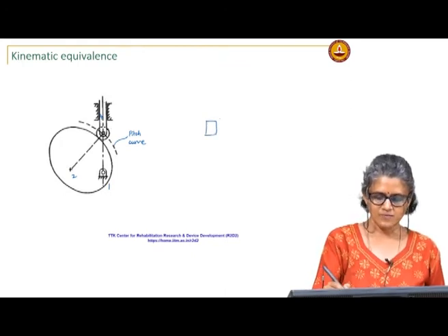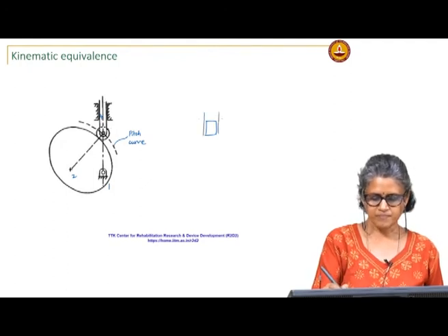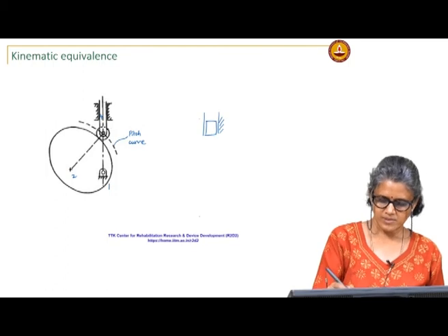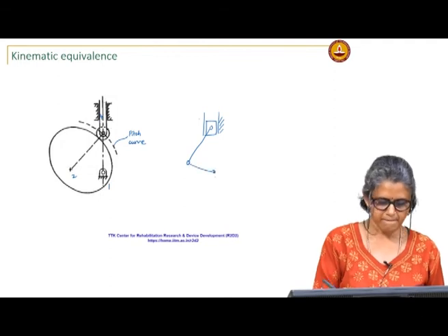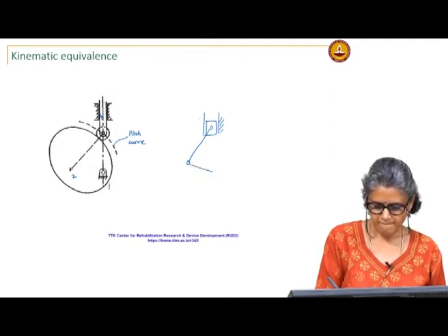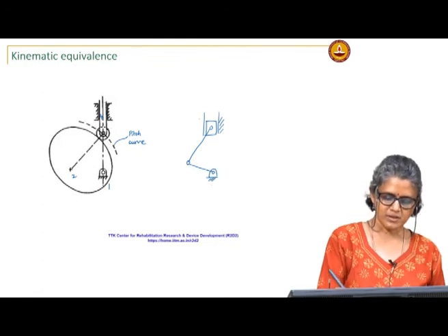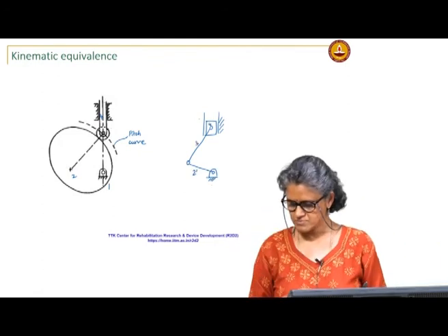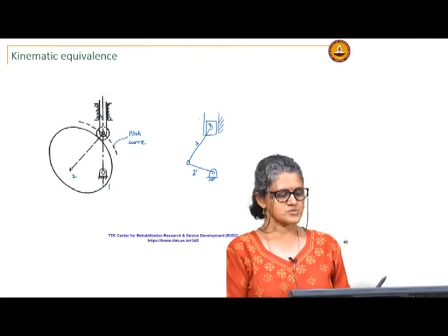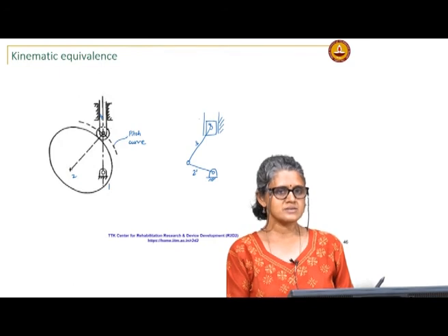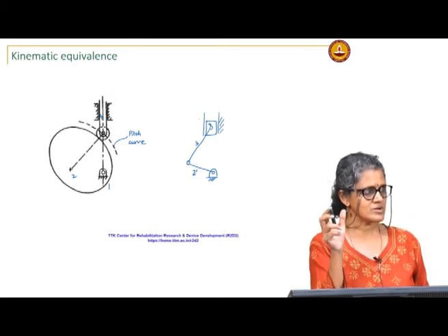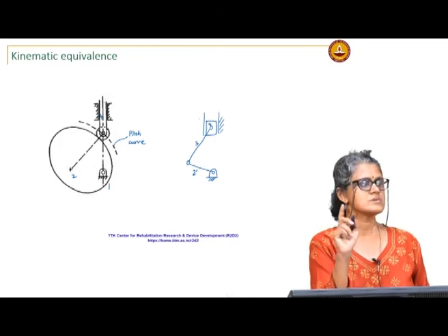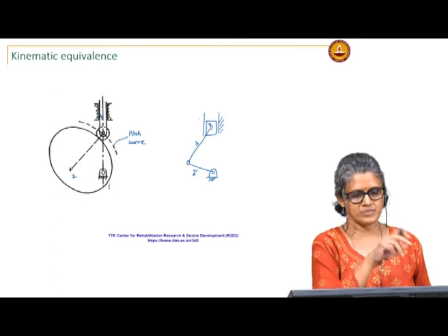It is moving with respect to 1, okay, and the motion of this would be equivalent to this would be 2. So, this would be the kinematically equivalent system with just lower pairs. We saw earlier for the pin in slot, okay. You separate the higher pair motion into 2 lower pairs basically.